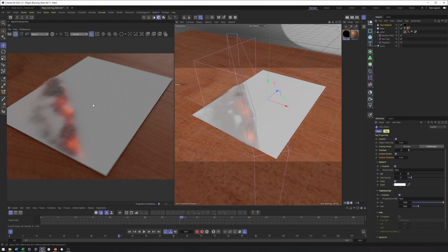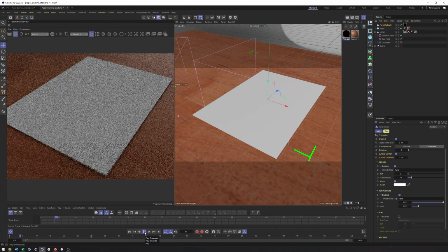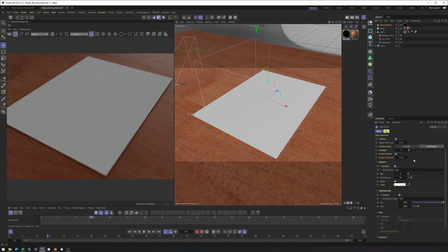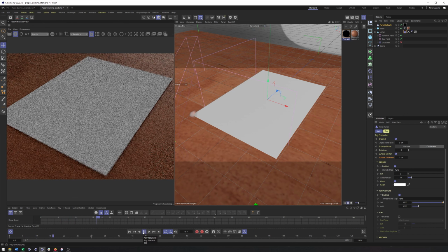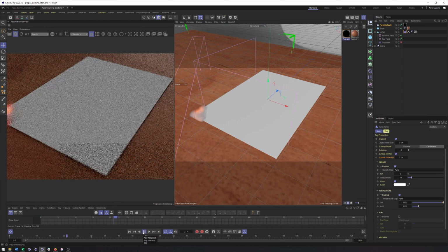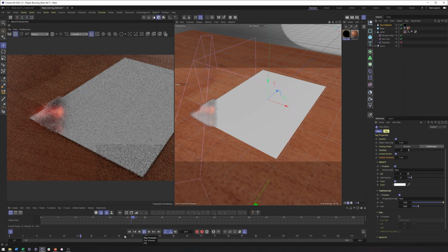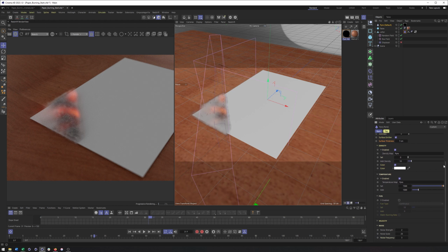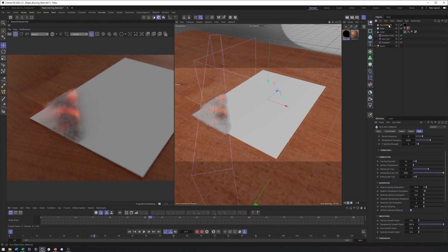The smoke now is a bit too dark for me. So there's always something here. And so that's why we're only going to do just a little bit more of this. So if we wanted to adjust the amount of smoke or have it dissipate a little bit faster, because that's something I've noticed as I was doing with this, the smoke sticks around a bit too long, and that can be a way to get less, is if you come in here to your Pyro object, and in the Pyro section, if you get rid of or increase the density dissipation here.